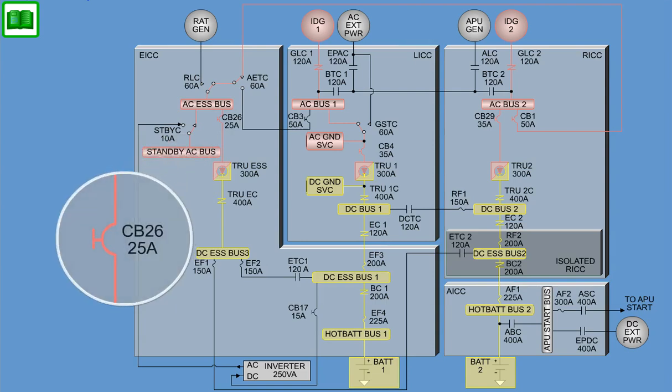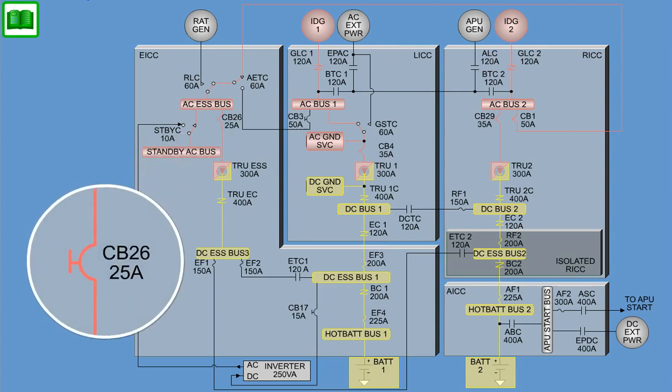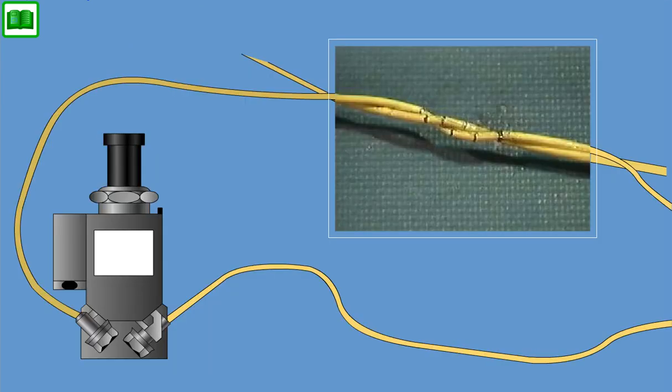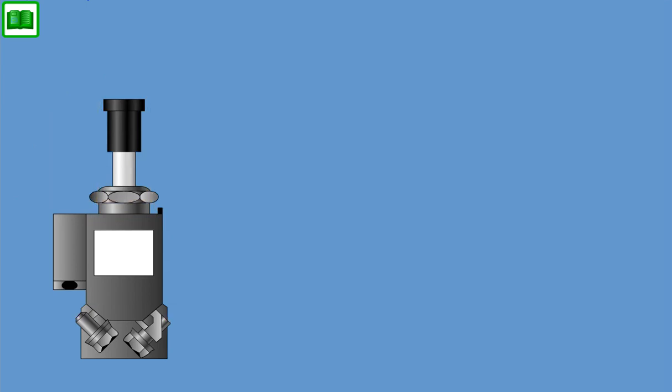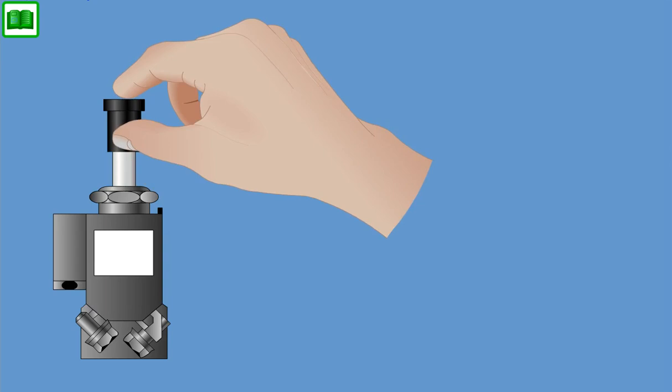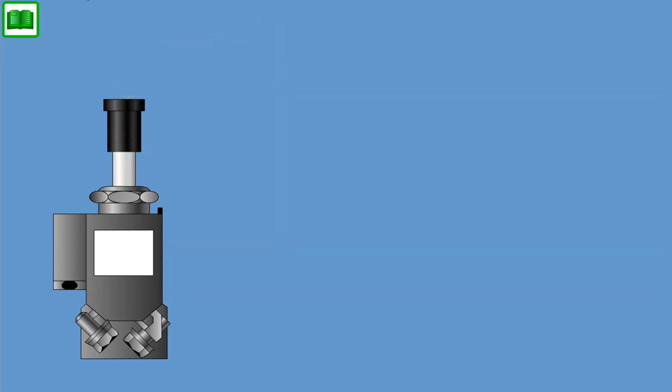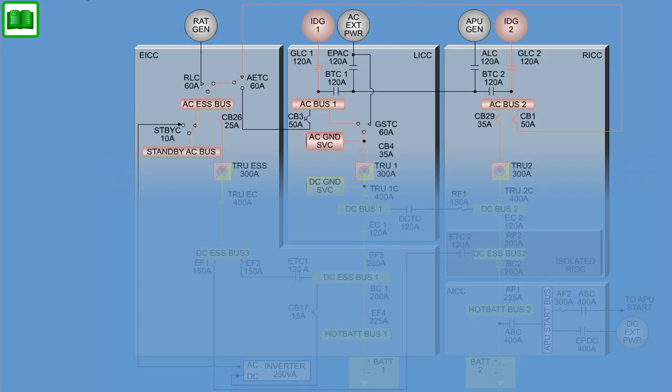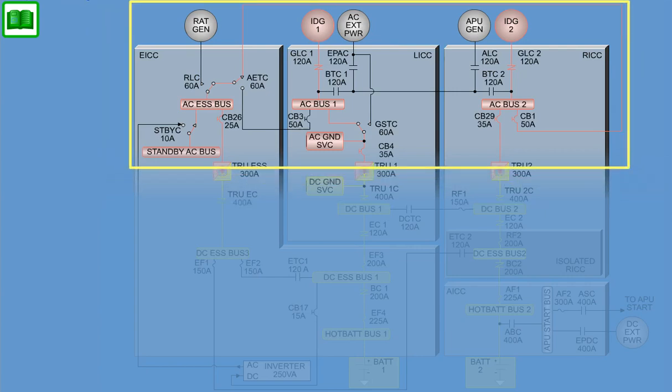The circuit breakers are thermal-type devices with temperature compensation. When subjected to an overload current, the breakers will trip open after a predetermined time. The circuit breakers are the free tripping, push-pull, on-off, manual actuation type. The CB auxiliary contacts are normally open, polarized with a blocking diode. The AC circuit breakers provide protection of supply lines and cabling for all loads whose power is sourced from the AC supply system of the airplane.